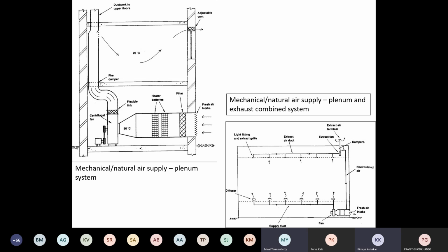No, yes, you can't have it, because you do not have the place for it. So probably you will have to cut the slab, bring the duct up, then cut through the wall, bring it out, and probably give the same window at the ground floor level. Okay. Now, when I say that, can you imagine a centrifugal fan?